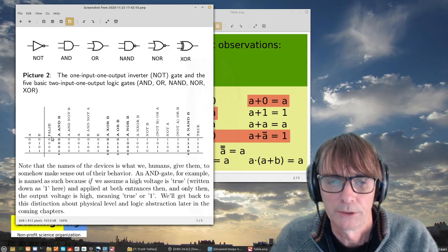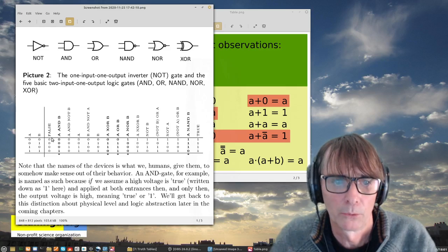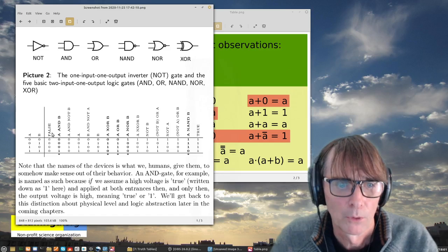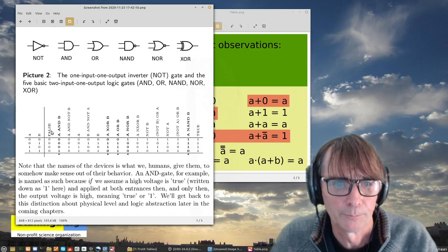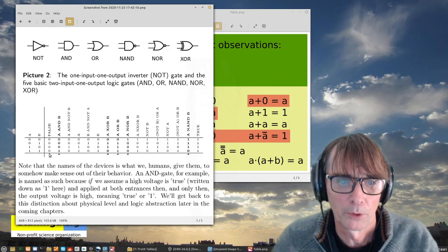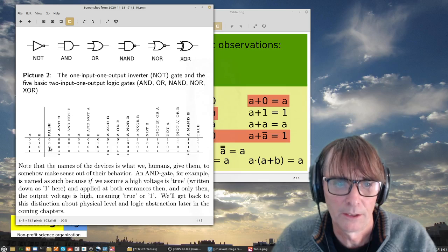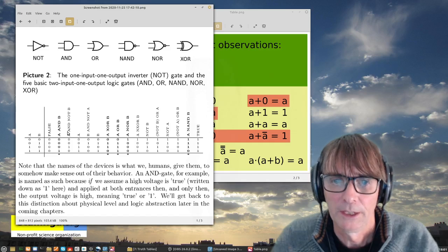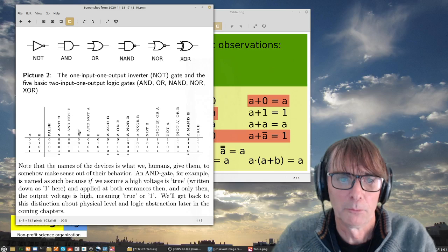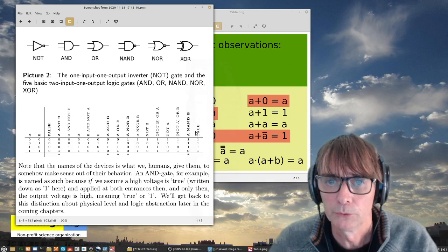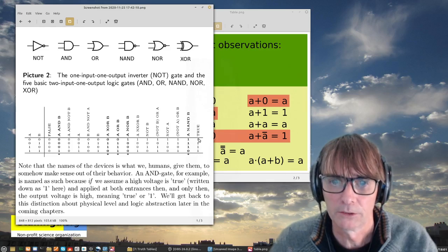I just call this ground, or more generally in mathematics, I would call it false, or simply 0. And then all possible combinations there are, because there are 4 bits here in the table. That means that you have 2 to the power 4, which is 16 different gates possible. Some of them are silly, I would call it. This is false, and this is true, which is always 1. The gate is called true.